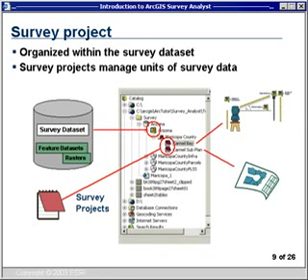The data from those projects can come from multiple sources. It was mentioned earlier that it can come from different instrumentation. So I can have a survey instrument, for instance a total station instrument, out in the field conducting measurements. That data can be loaded into the geodatabase, in this particular case, into the Carmel Bay folder. And then I can perform survey operations and computations on that data. Other data, such as from this subdivision plan, can be entered into that database using coordinate geometry procedures, where you type in the angles and the bearings and the distances that define those features.